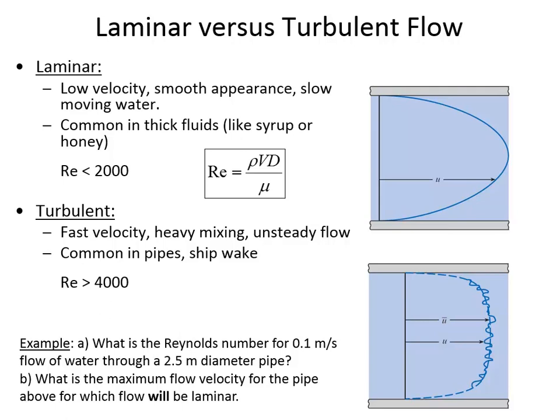And so water flowing through a pipe at 10 meters per second is still going to have turbulence. And that just gives you an idea of how rare laminar flow is. Most of the time when we're doing calculations for water flowing over a dam spillway or water flowing through a pipe network, almost always it's going to be turbulent flow. It'll be very, very rare for it to be laminar conditions.